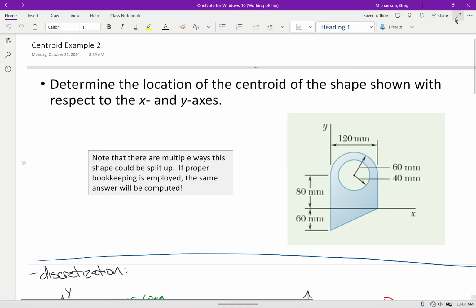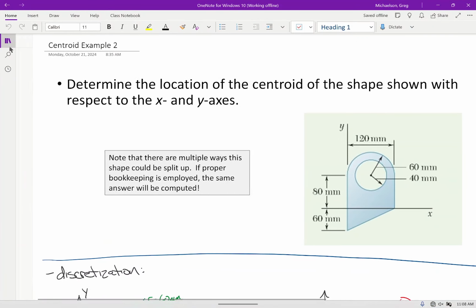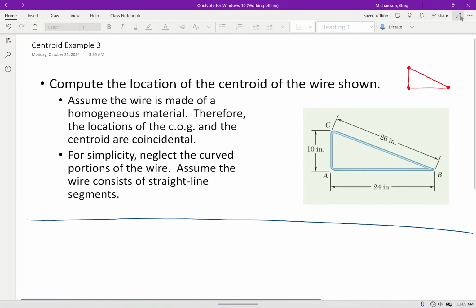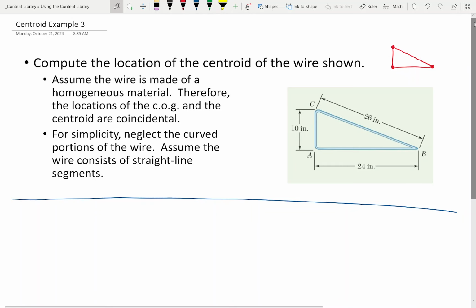However, now that we get the idea, what we have to recognize is that as engineers, we're going to have to choose our own coordinate system. Okay. Now, what I'm going to do is choose my origin at A. I think that's kind of the natural place to put it. So we'll say this is the y-axis, and this is the x-axis. The reason I'm choosing that location is that when I compute the centroid, the coordinates are all positive, right? There is nothing, quote-unquote, correct about that strategy.